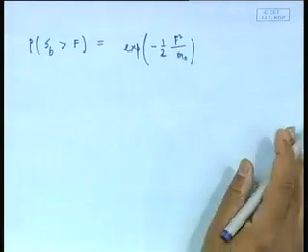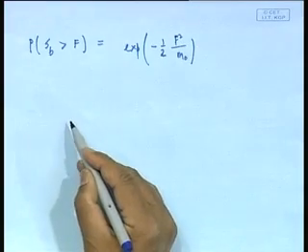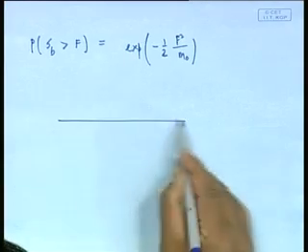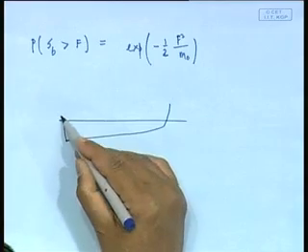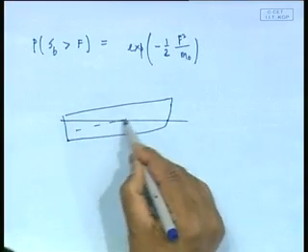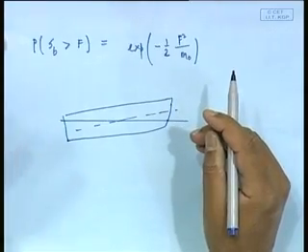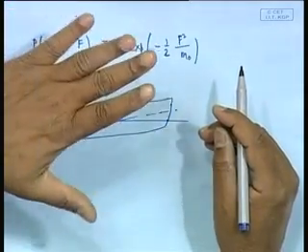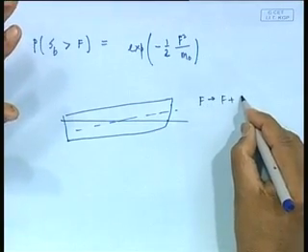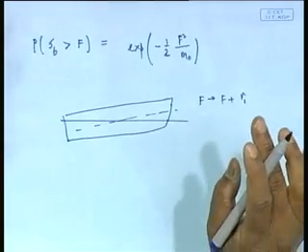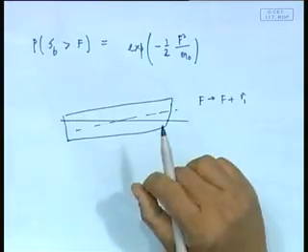Now before I go to this threshold value, there is one more thing I want to tell you. As far as the threshold value is concerned for deck wetness, two more modifications are made to the freeboard, because when I take a ship, as it goes in calm water itself, it actually undergoes a kind of trim and squat, because it changes the value slightly, as it will actually have a parallel sinkage and a trim. So that modifies this f to f plus some correction, say R1 let me call. So therefore the effective deck freeboard threshold value that you get may get modified.